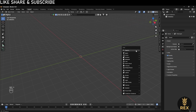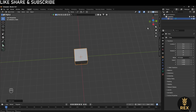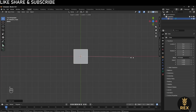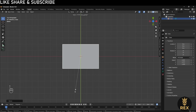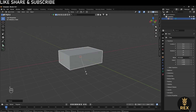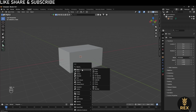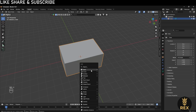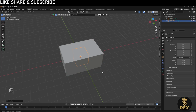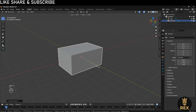So we will press Shift A, then go into Cube, then look at it from the Z axis and increase its size, first in the X and Y axes, then in the Z axis. You might be thinking what type of table I am creating, but stay tuned, you will know. It's a very easy table, so you do not need to think about it.